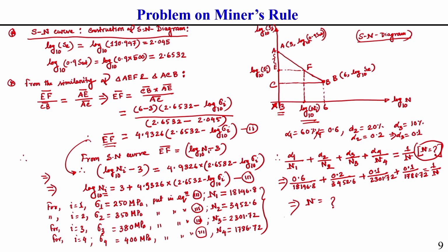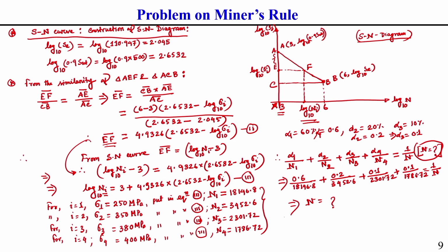So, this is the technique by which you can find the total fatigue life of a structure using Miner's equation. Generally, we can calculate the cumulative fatigue damage of the structural component, and we can say whether the structure is able to take further loading cycles or not. And when it will fail, those related things you can also calculate with the help of this Palmgren-Miner's rule.